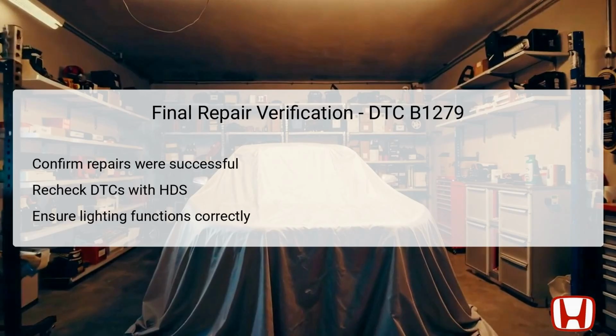This involves confirming that all repairs executed have been successful and effectively resolve the underlying issues. Begin by rechecking the DTCs using the HDS to determine whether any additional codes remain present. If no DTCs are indicated, it suggests that the system has returned to optimal functionality. Lastly, ensure that all the vehicle's lighting functions correctly, including the brightness levels controlled by the dimmer switch. Successful verification solidifies that the repair process has been correctly performed and ensures the vehicle's lighting systems are operating safely.